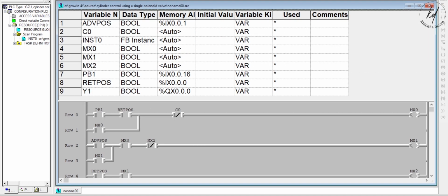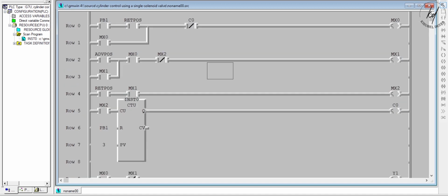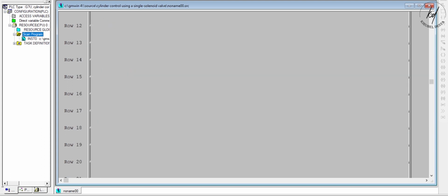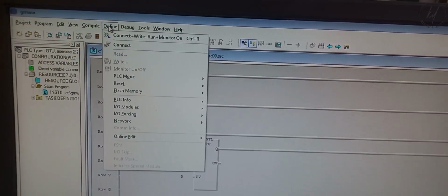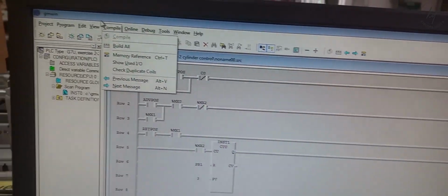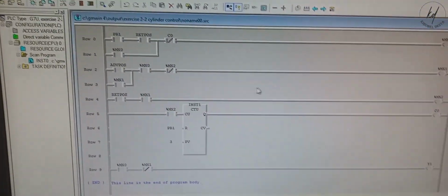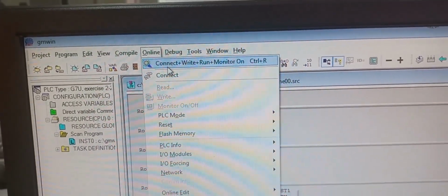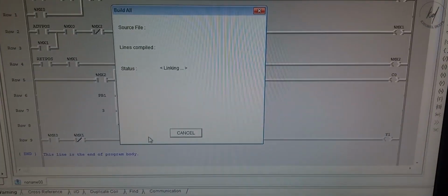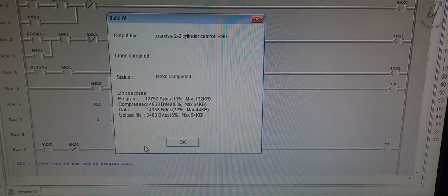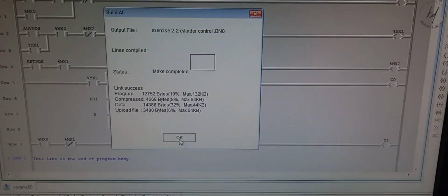To understand what is going to happen as the push button is pressed: as the push button is pressed once, the first memory, which is MX0, gets supply from the rung and self-holds its circuit. Now it is independent of whether the piston is in the retracted position or the push button is pressed again, and as I have said earlier, the only thing that is left to activate the supply cylinder is MX0, which is now made and energized, so it changes the cylinder piston from the retracted position to the advanced position. This helps the second memory address MX1 coil tag get energy. Due to this, on the other side it disrupts the cylinder piston activation, so that it will retract.